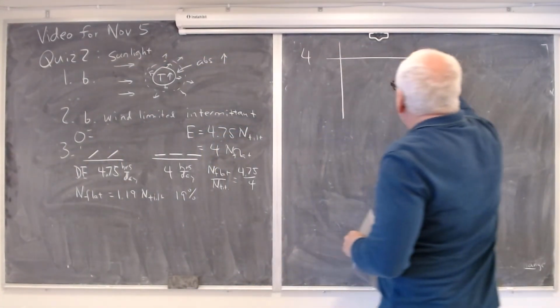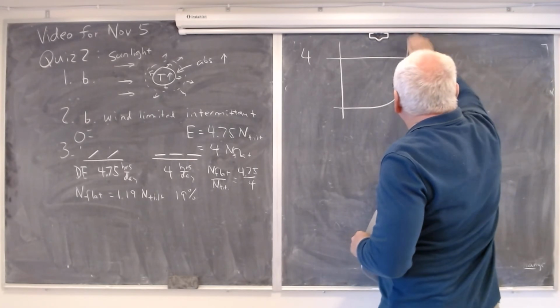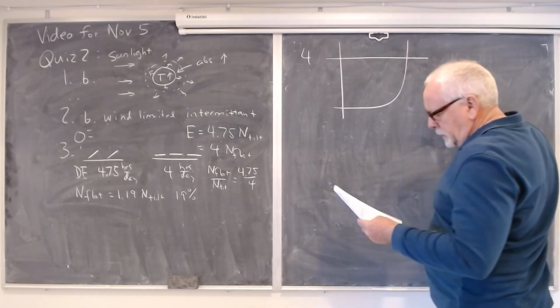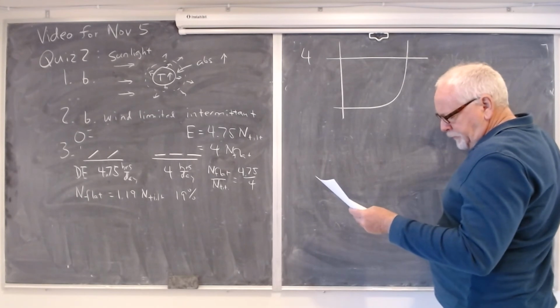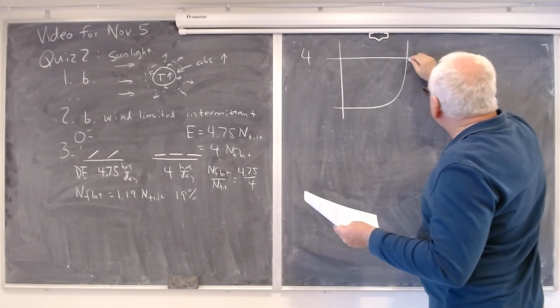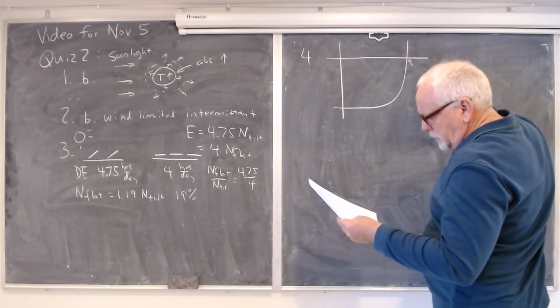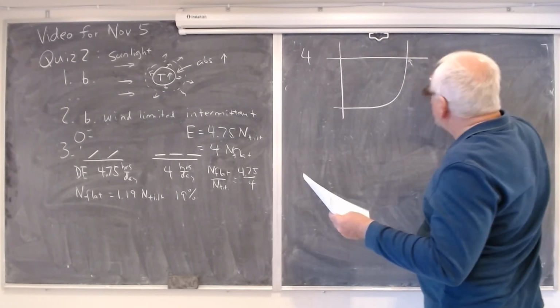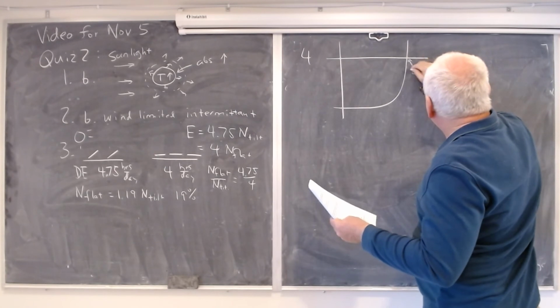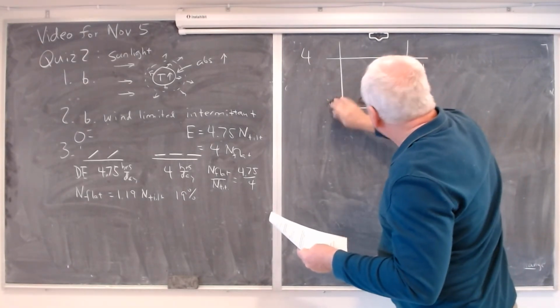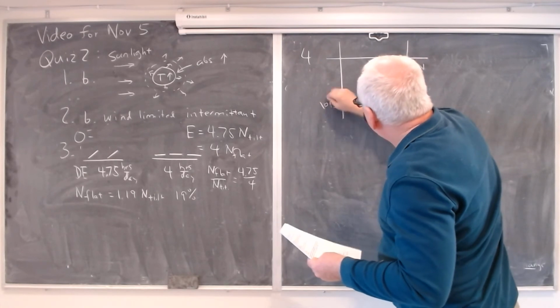Okay, you were supposed to take this IV characteristic, and you were supposed to determine the maximum power, and so basically the idea that this crossed at around 28 volts, and this crossed at around 10 amps.